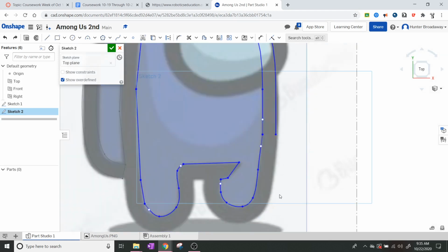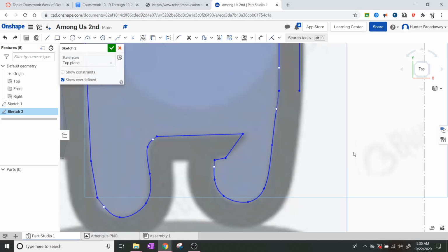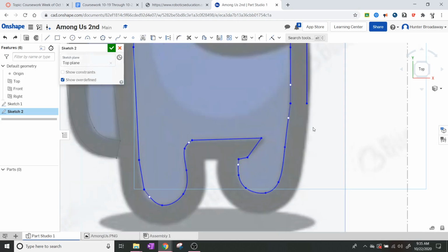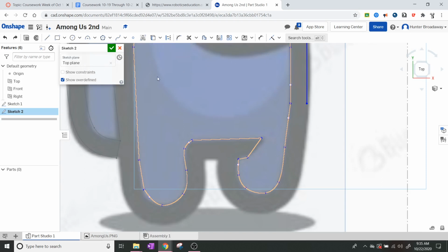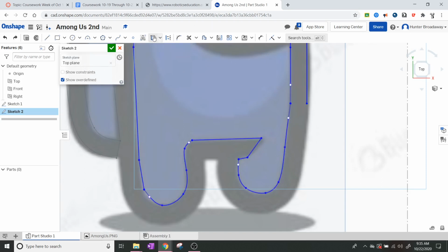So, I don't know. Maybe it's just time to spline again, and that might make our life as easy as possible. So I guess I'll try that. If I use the spline tool and just start going around the outside, that's just what I did, and I was done. I was just trying to look for fancy solutions, and in doing so, it ended up costing me more work than just using the spline tool. But if you get to this point right here, see how it starts to weirdly curve around? I would stop the spline right there, and then I would make a new one.